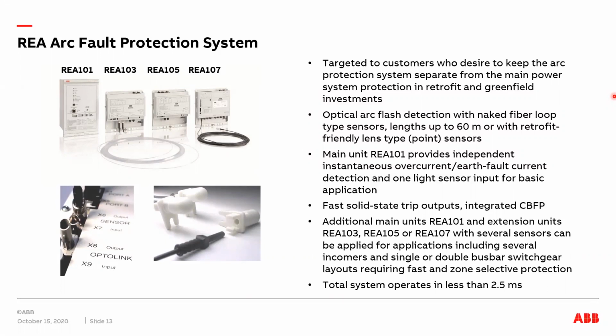There is a possibility to use only light detection without overcurrent detection, but since some spurious light can then cause unintended operation, we recommend to secure the optical detection with simultaneous arc fault current detection.